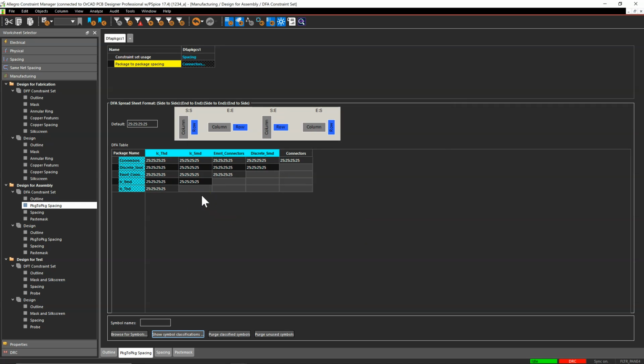See how the groups are organized. And then you can go in to each one of these and change these values. Like 90 mils, if we're talking about the edge of the connector compared to, or distance from, the edge of an IC SMD or the side of an IC SMD. So I'll repeat that. The edge of the connector, the short edge of a connector, would be 90 mils from the side of an IC underscore SMD part.